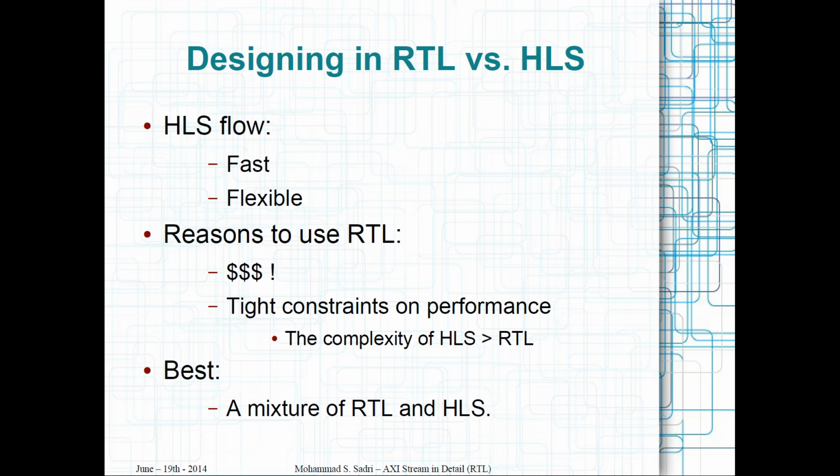Especially, just imagine you are dealing with floating point calculations, and your module should handle floating point numbers, and at each stage of your processing pipeline, you have a different precision. If you directly want to code these things in RTL, it's really time consuming, while in HLS it's really fast. But at the same time, for some specific parts of the code, maybe it's still better to code in RTL instead of HLS.